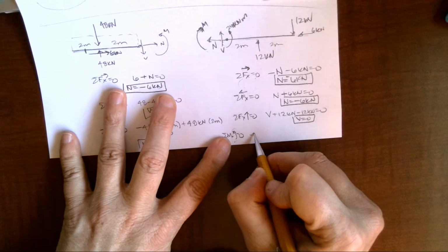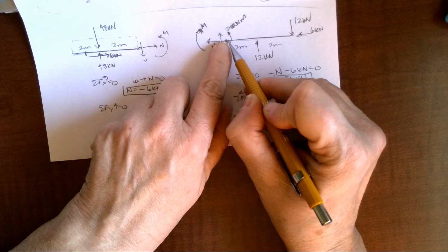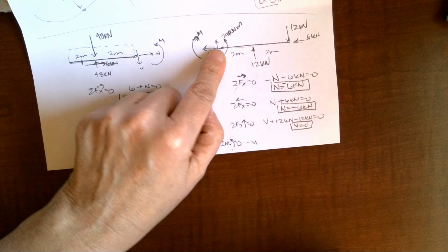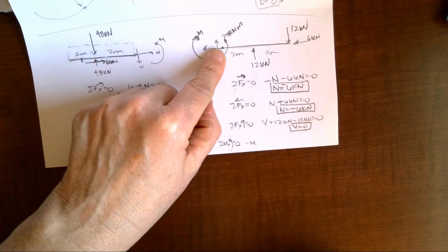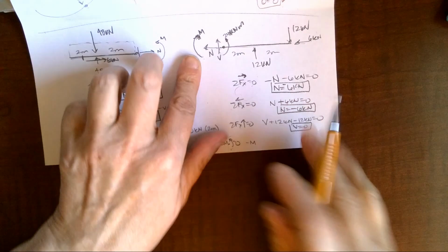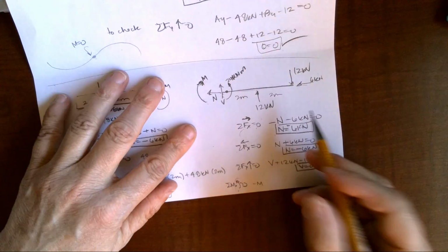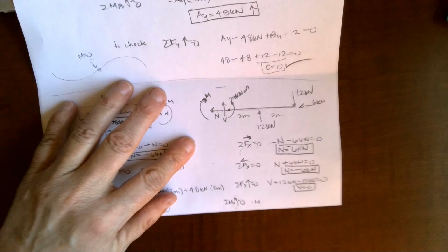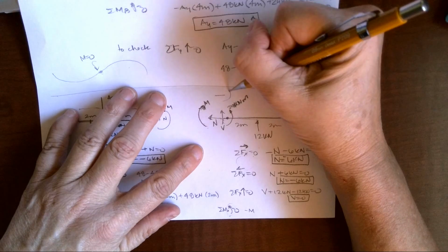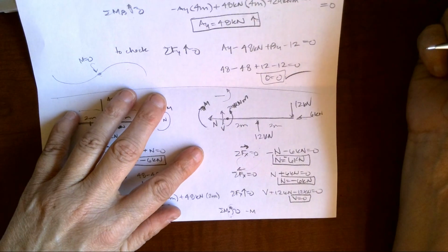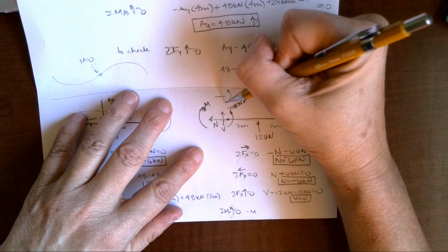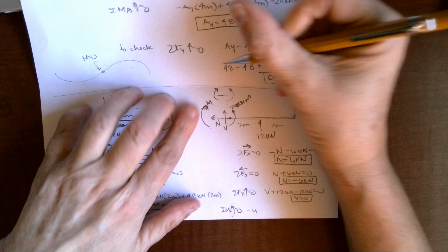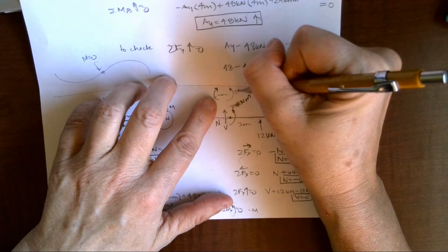Okay, and then I come just past that cut, and I have this applied moment of 24 kilonewton meters. And I need to know, is this a positive moment or is this a negative moment? So you guys know, I'm really weird. I'm going to draw my cut just right here, like a millimeter right at my cut. And I'm going to show that I have this external applied 24 kilonewton meters. So if at this cut, just looking at this applied moment, it needs to be in equilibrium, I know that my internal has to be equal and opposite. Otherwise we would have rotation.